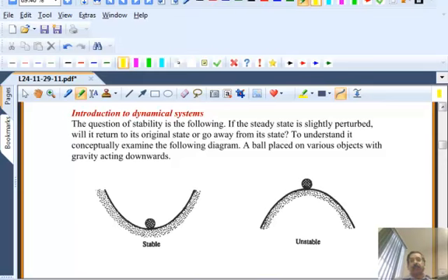The next topic, which I hope I will start and finish today, is hydrodynamic stability. Okay. Right from the beginning of this course, when we were talking about solving for pipe flow, the parabolic profile, we asked the question: does that profile remain valid for any Reynolds number? And the answer we sought was experimental evidence suggests that it is not. After a Reynolds number of 2100, that parabolic profile fails to be observed in an experiment.